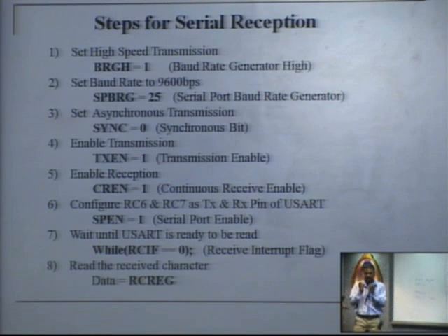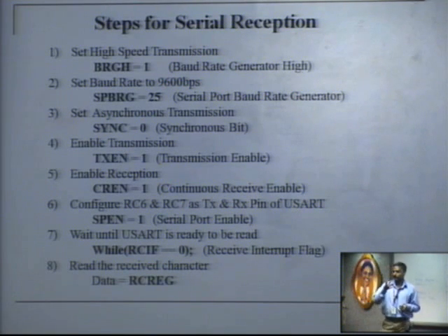Then you can also write something. For example, I have read the character A. How will I show that? I have read one character and I need to show that, no? So you can retransmit it back. For example, you are communicating between PIC and PC. PIC is receiving some data, and I don't know which data is being received. So what will you do? PIC will receive that data and retransmit it back, so in the PC you can see.